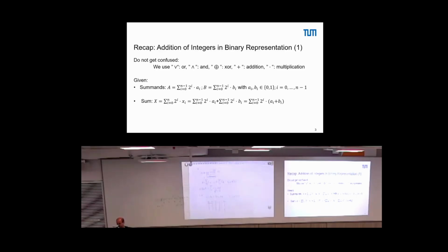Good. Well, what did we construct? This here can be interpreted as we have either A or B. So, this here is A0 XOR B0 equals S0. This here is only if the 2 are 1, then we should have a result, output 1.